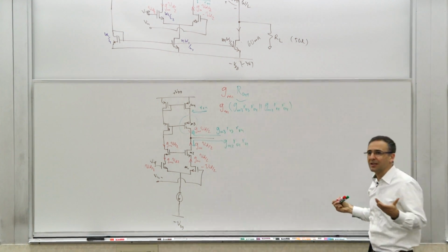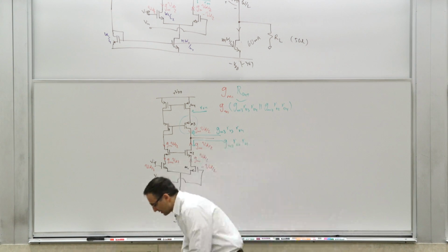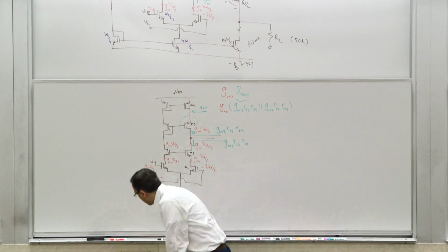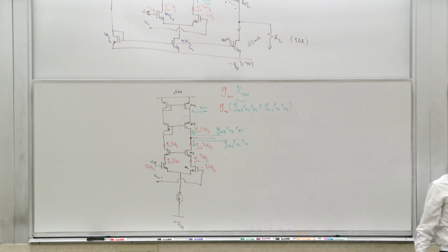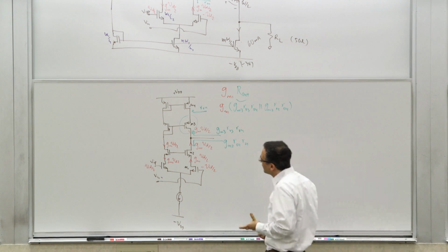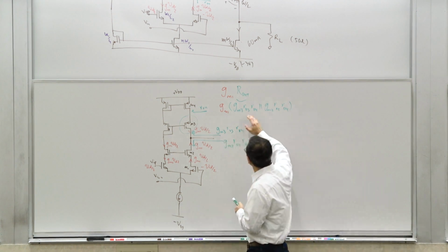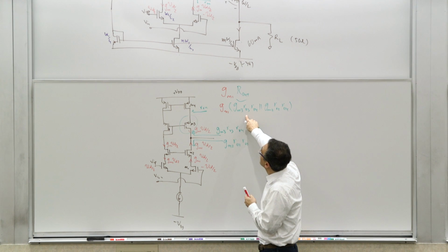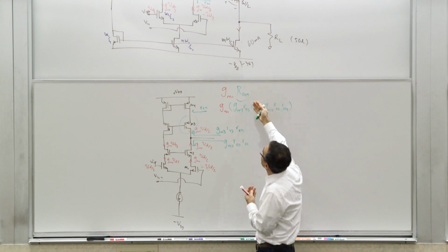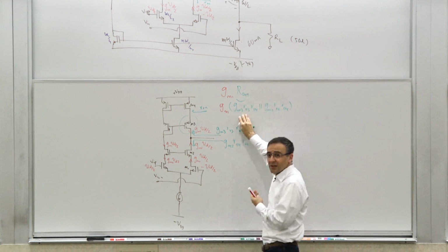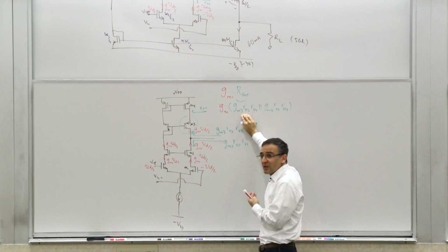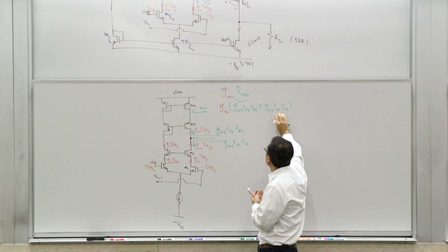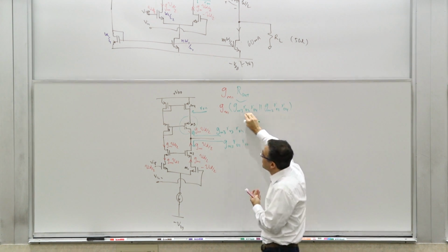There are so many different combinations of these things, right? That you need to understand how you arrive at them as opposed to the specific answer for the specific solution, because every time it looks different. Now, this at least appears to provide more gain, right? Because the GMRO based on the numbers we wrote are in the range of 100, right? So we go from 25 kilo ohm-ish times 100, this becomes 2.5 mega ohms, parallel 2.5 mega ohms, times 4 millisiemens.